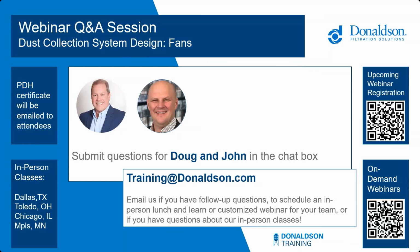Thank you. Next question. Should we consider vibration monitoring on these industrial fans, especially as our motor horsepowers start to get pretty large? Absolutely. And that's kind of the key where the cost efficiency comes into play. Larger fans and larger bearing systems get more complicated and of course much more expensive. And monitoring is not that difficult and not terribly expensive.